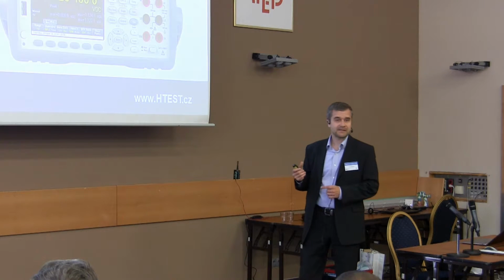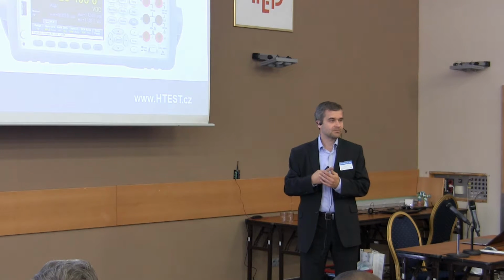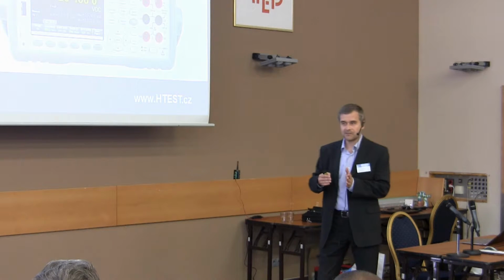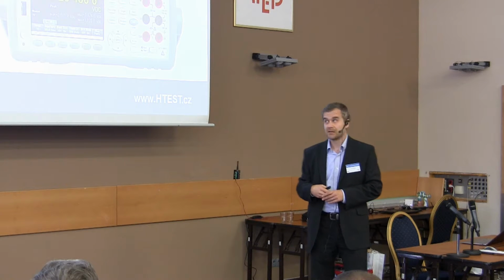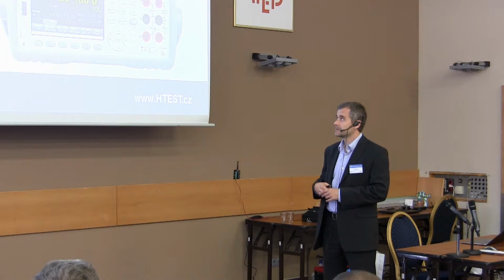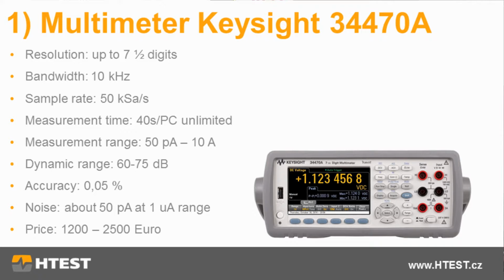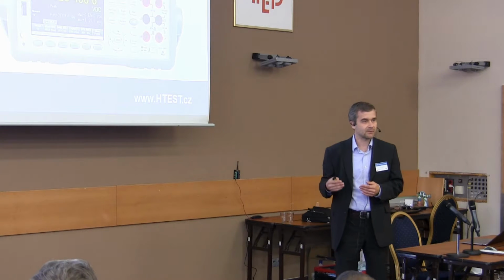One is that if you want to measure very precisely, you have to take one measurement for a longer time, and then you miss some fast states. Second, it's not measurement in one range. When the multimeter is auto ranging, it takes some time. Although it is quick, it takes some time, and again you can miss some details of the signal.